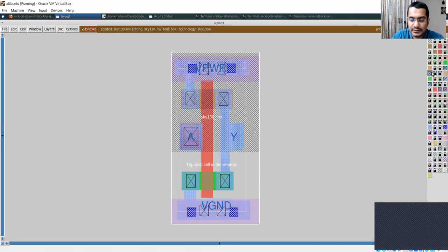The next step is to deposit a thick layer of SiO2. There is something special about this SiO2 that is being deposited over here. It's being doped by phosphorus or boron. There are multiple reasons to do this. One of the reasons to dope it with phosphorus is that phosphorus acts as a protection layer for the sodium ions. There are some mobile sodium ions that flow inside this SiO2, so we need to take care of that. Phosphorus acts as a barrier or protection against them. We'll talk more about that when we enter into VLSI technology classes, so let's not talk about that over here.